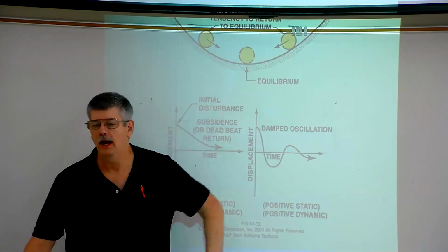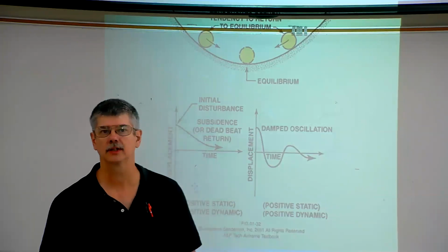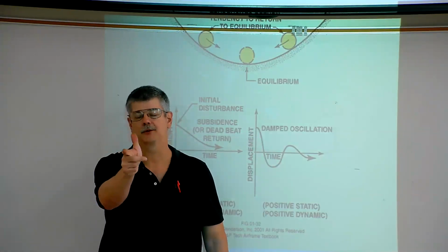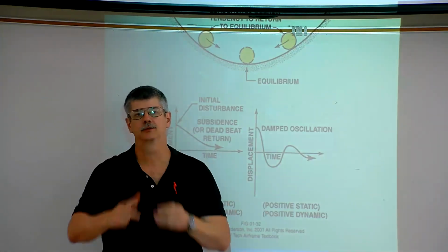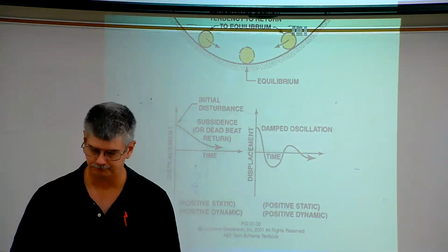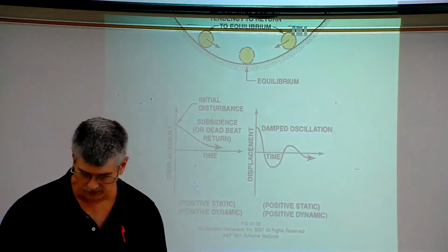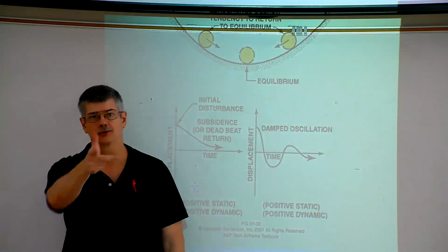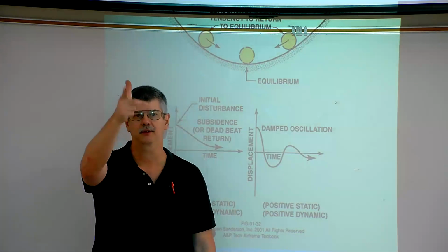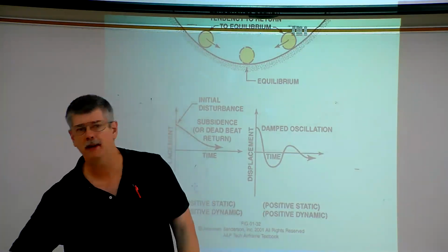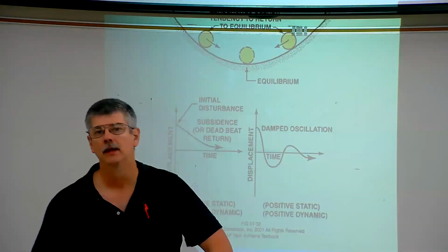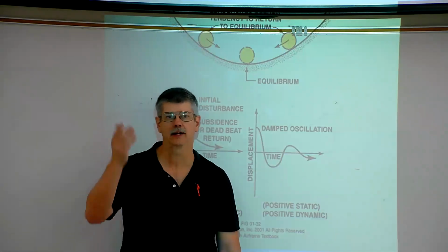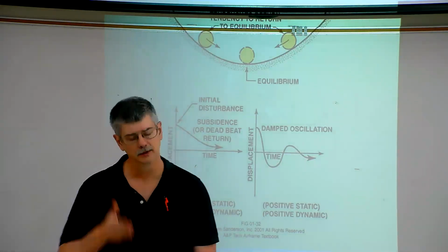Okay. And then what makes an aircraft directionally stable is the vertical fin. If the aircraft yaws, air will hit it and straighten out the aircraft. From there, we talked about the control systems, with the longitudinal control, which is pitching the aircraft up and down, would be done by the elevator. Keep in mind, the elevator, if we pull back, the elevator goes up to make the nose go up. Down.